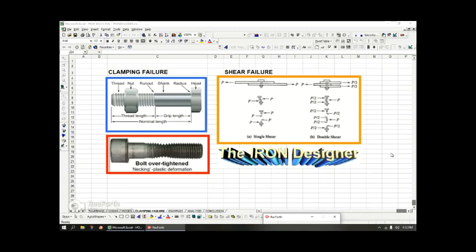The nut is what's applying the clamp load using torsion, right? So as you torque the nut, then the bolt begins to stretch due to tension in the bolt. You have tension in the threaded length, and you have tension in the grip length. So remember, the grip length is primarily to oppose shear, but no matter what, you still have the nut on the thread length, so you're still going to have stresses in the runout, okay? Then, of course, you have the threads, and the overall length of the bolt is measured from the bottom of the head, and that's called the nominal length.